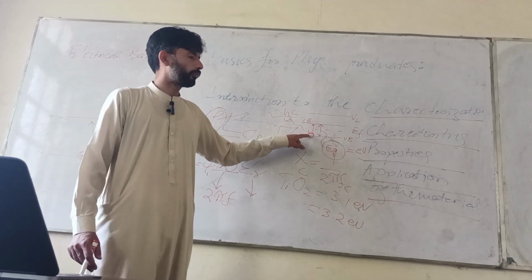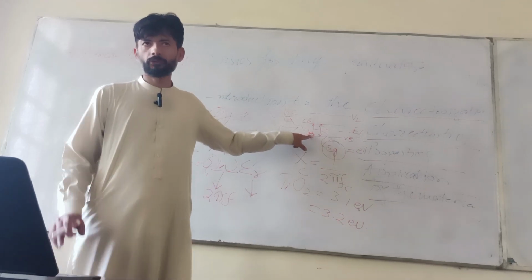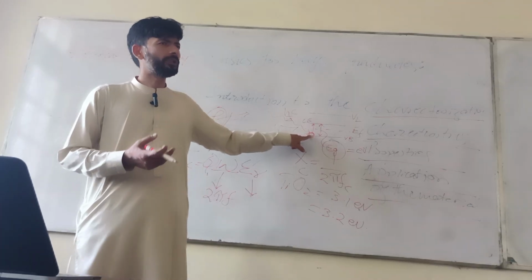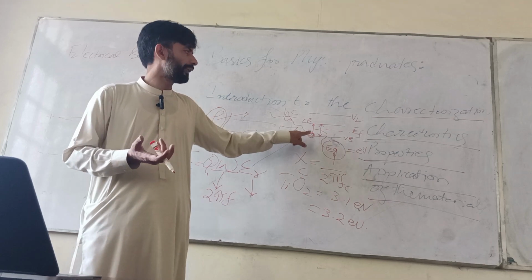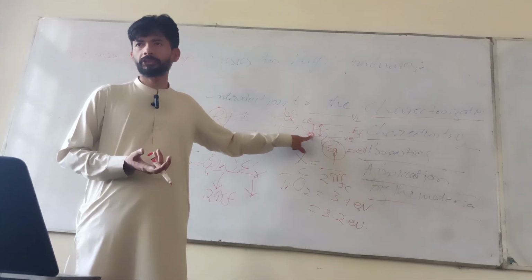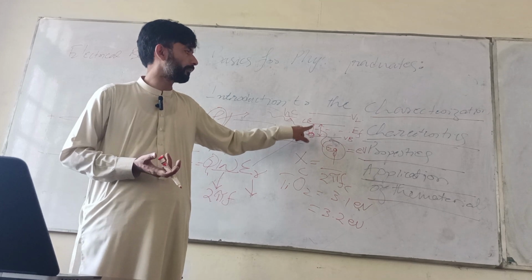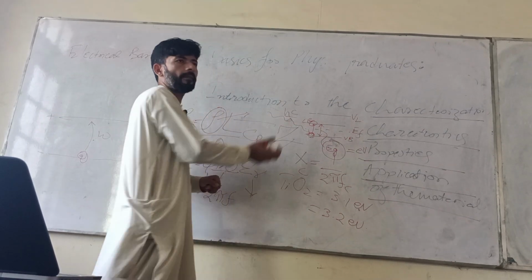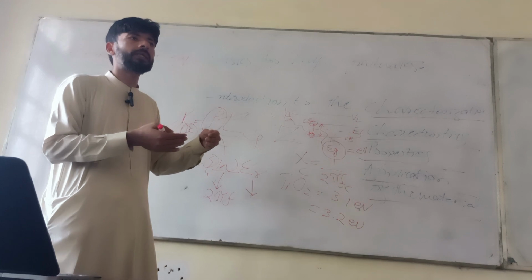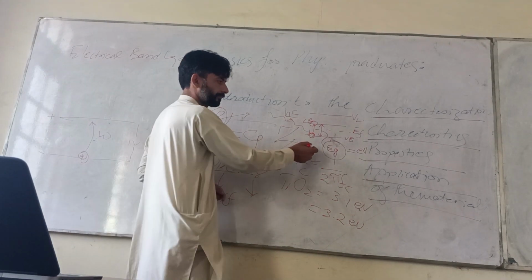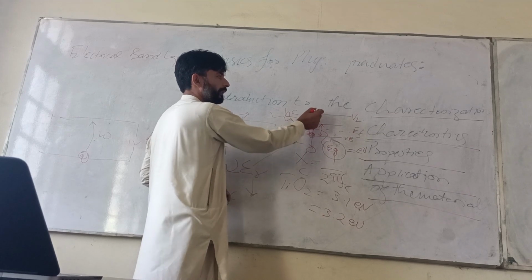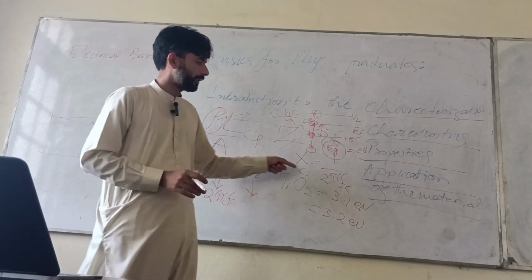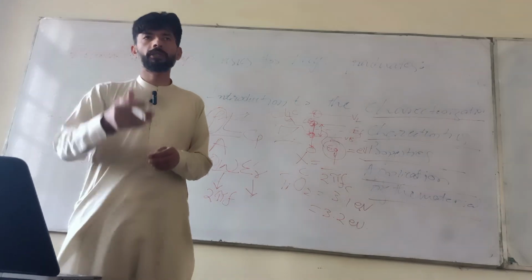In that case, Coulombic forces, you know Coulomb's law, the force of attraction and repulsion, exist on that electron when it jumps from the valence band to the conduction band. In the conduction band it is still interacting with the nucleus. Forces exist there, but at the vacuum level there are no forces. That's why the electrical band gap is a few electron volts above the optical band gap.